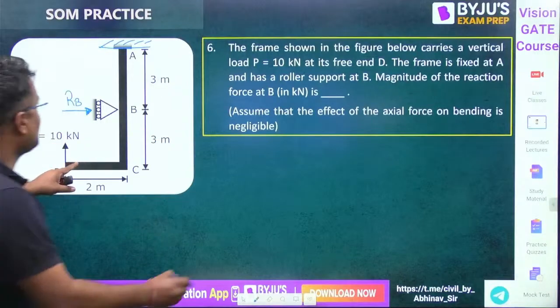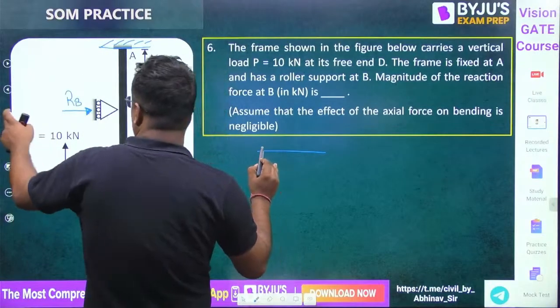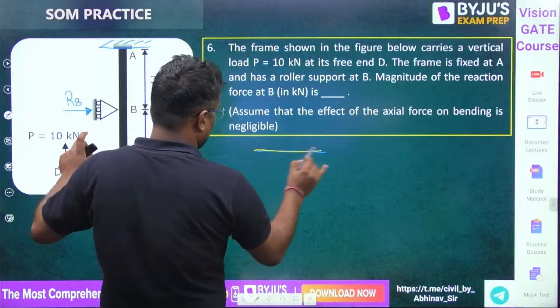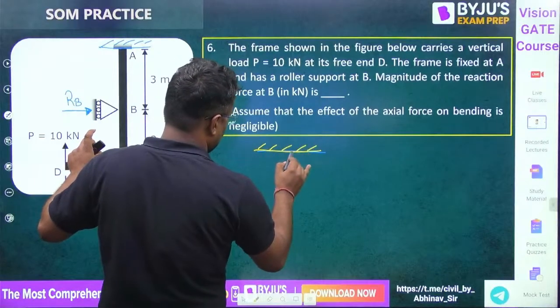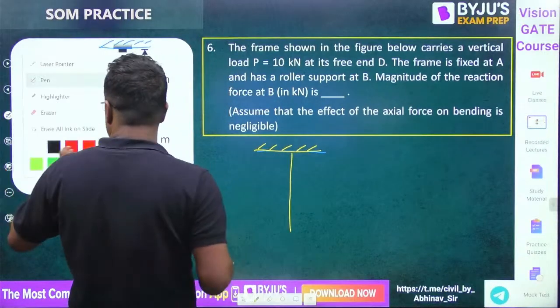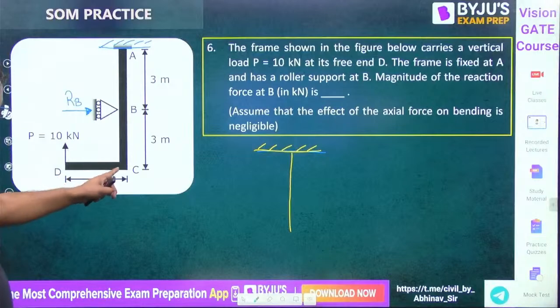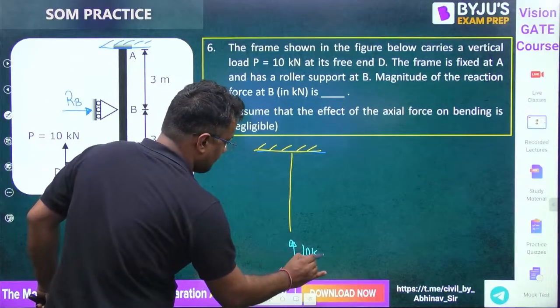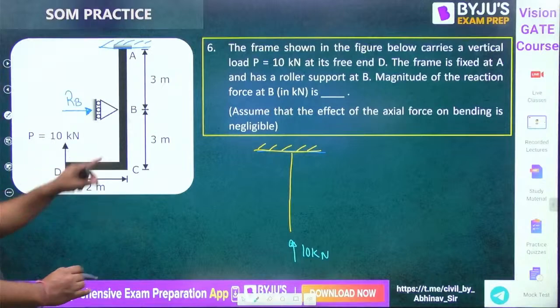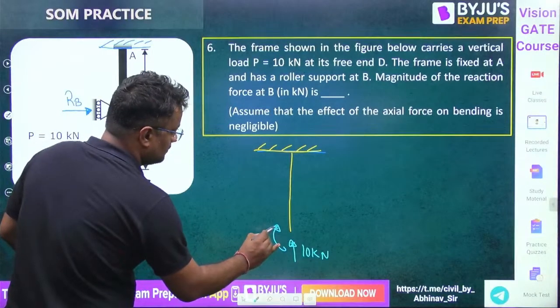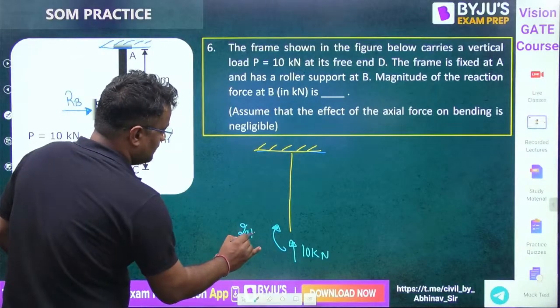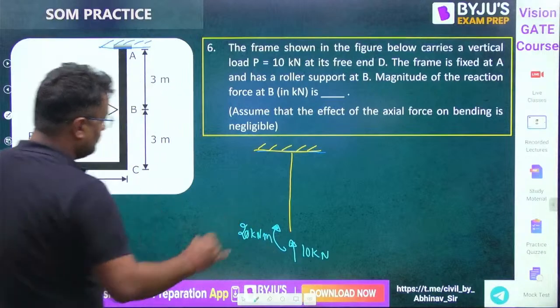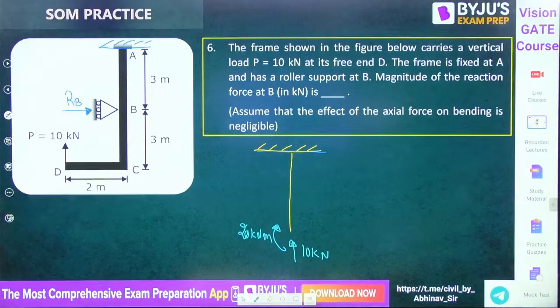Sir, will I be able to do this question? Now, if I transfer this load here, it is 10 kilonewton, and this 10 into 20 moment, 20 kilonewton meter moment, I am transferring here.